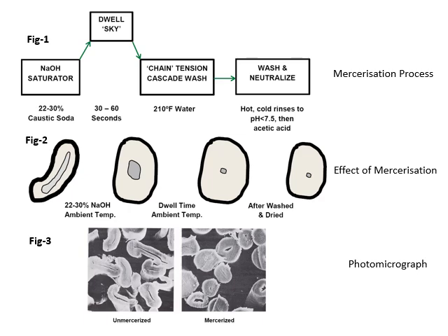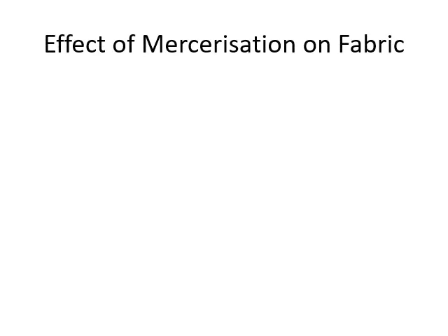Definitely the thickness of the wall is improved, and the lustre and shining of the fiber at the end is at a higher level as compared to the unmercerized fiber. The positive results of the mercerization process include increased dyeability and uniformity.